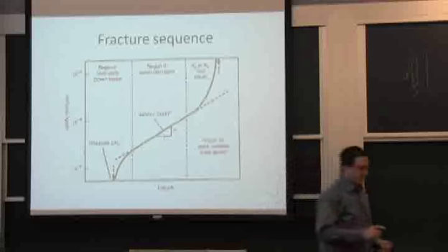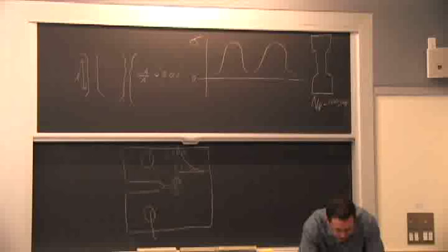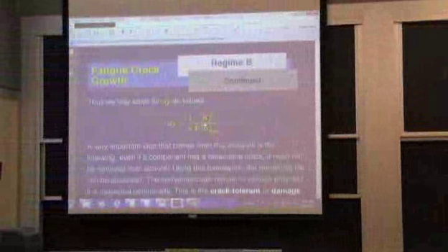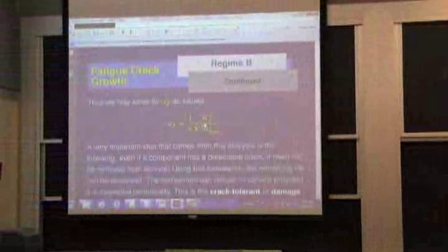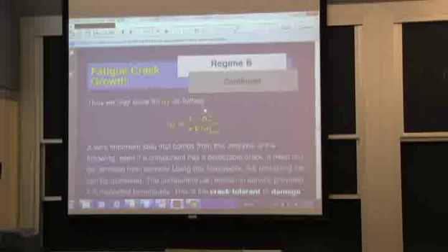It could be more of a problem, and that's the reason I was mentioning it, for using the equation here. Because this equation takes you all the way to the failure load, and if your part is too small, it's possible you cannot use it. But there are other methods; I mentioned the J integral in the introduction. It's a method that will allow you to take into account that you have a lot of plasticity in a small sample, and do the solution very precisely, but it's a lot more effort. It's based on the same general idea, but it's just a lot more work.